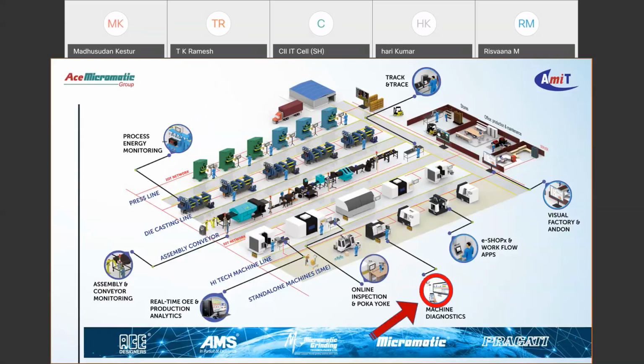We also have systems which help the maintenance department to understand the machine performance better in the form of machine diagnostics. These solutions are available on later controls like Fanuc 0i-TD and above, like Fanuc level, and Siemens 828D and above with OPC capability. Or it can be a Mitsubishi control, some other control, etc., where controller supplied API libraries are available. So you can dig deep into the control and generate a lot of useful information for the maintenance person.